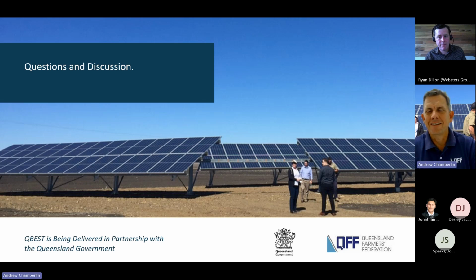Yeah, excellent, thanks. And then, as the day winds down, the heat tends to drop off as well as the solar generation, which is obvious, but you may decide to leave the doors closed after 4 p.m., for example, to stay within your solar generation envelope. Make sure that the condensers and fans are being used as little as possible after that time.